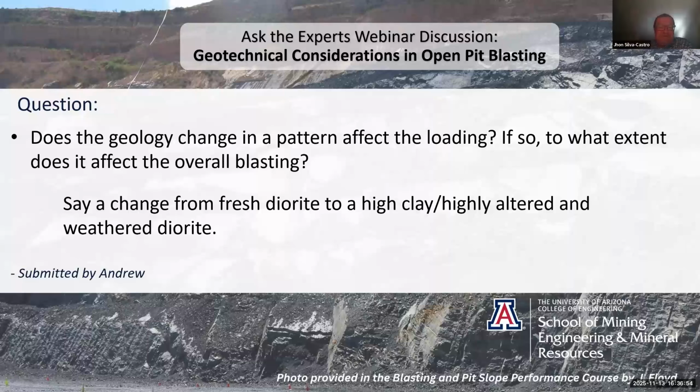Yeah, definitely. When you do the blast design, there are some factors to consider, and one of them is the impedance. So definitely, you want to apply to the rock the energy according to the rock strength. So definitely, it's different. Different materials need different explosives, and that will optimize the results. So that would be the straightforward answer.